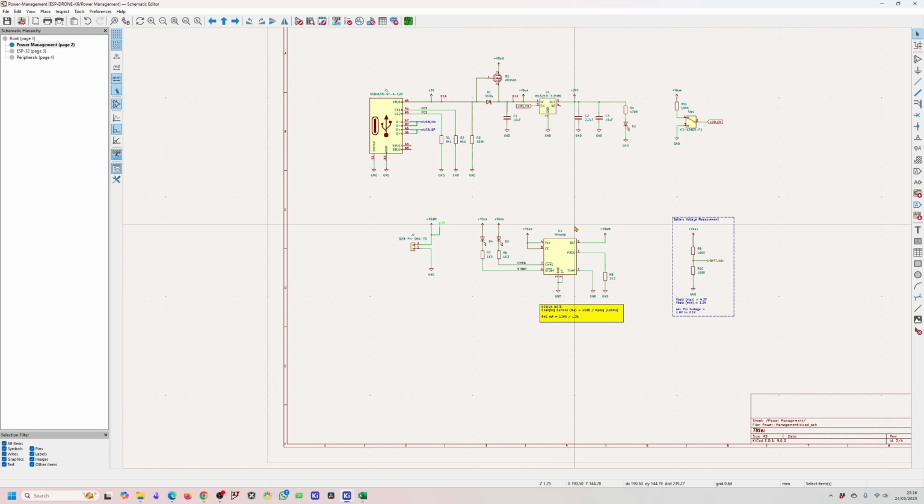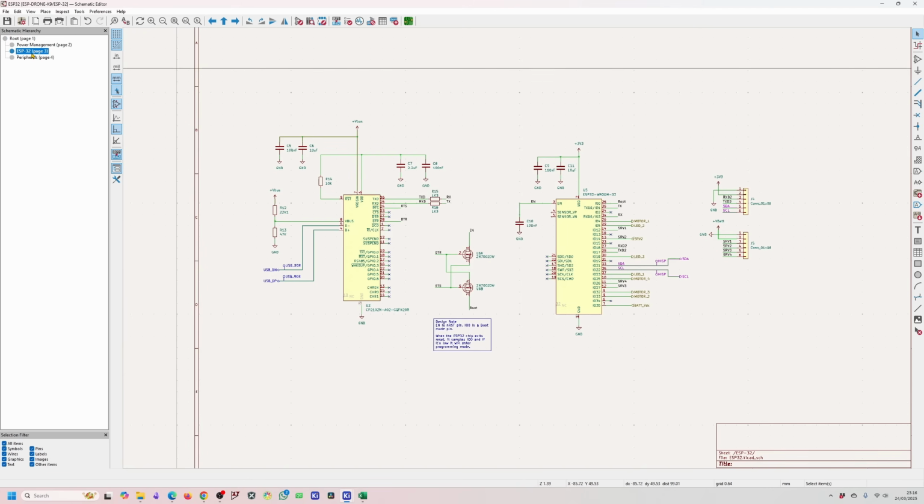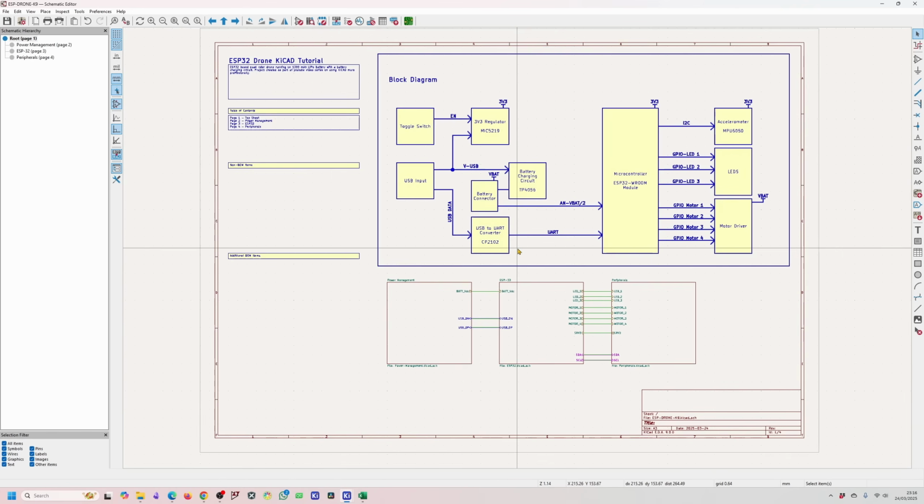In today's video, we have gone through net classes in a lot more detail and how it affects the PCB design side, how we can use net classes to our advantage in order to reduce errors, and basically a form of automatic rule checking. In the background, not on video, I've completed the schematic itself, but I've not used anything new in order to do that.